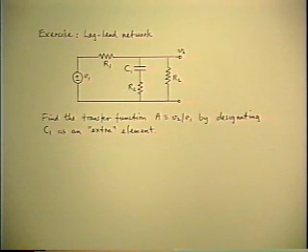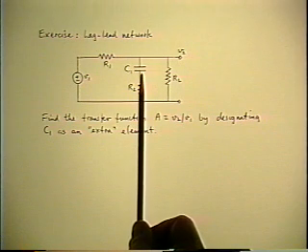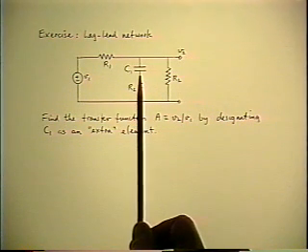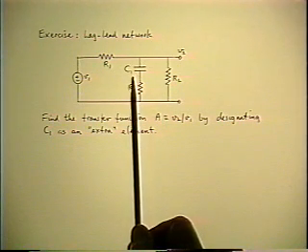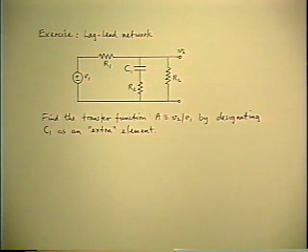And you notice that first thing is, even after you've chosen the capacitor as the designated extra element, and you throw it away, you're faced with a choice again. What do you replace it with, an open or a short? Yeah? Why? Well, in one way, R2 isn't going to come into it. It isn't going to come into the reference gain, but it is going to come into the driving point resistances.